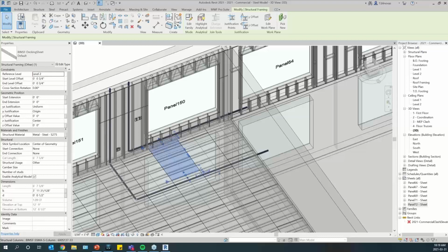Thais, one of the questions that came through: does MEP Clash work with linked files? Yes, it works with linked files. You just have to be careful if it was converted to something else, just to make sure the linked file is okay, and that you can actually tab between members and select one member, just to see if everything is good. But yes, it works with linked files.